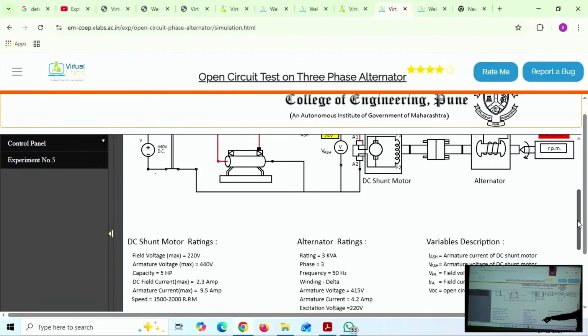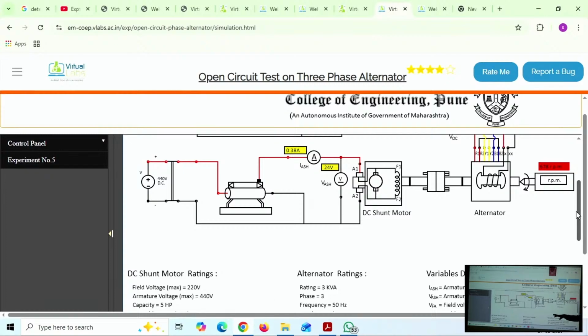Yesterday our HOD sir was telling us about the hydraulic power plant control system, guide vanes, how the water flow is entering. When the load is approaching, we have to give more input. How? Not all of a sudden, because that is water flow through the penstock. Penstock water flow control is not that easy that you suddenly close everything and suddenly open. No, the penstock will be subjected to more pressure. That entire system must be balanced in all aspects, mechanical as well as electrical. So we should take care of currents below and above the rated currents.